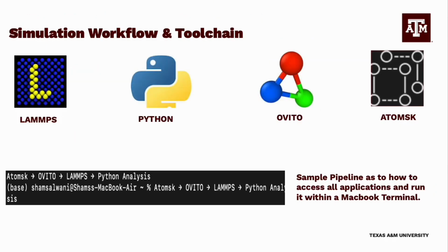To investigate these questions, I used LAMMPS, a molecular dynamics simulator, and OVITO, a 3D visualization tool specifically designed for atomic-scale analysis. The simulation process began with building a supercell of NiTiHf in its B2 phase. Some structures were pure crystalline, others included precipitate atoms, which I introduced by substituting atoms within a defined spherical region.